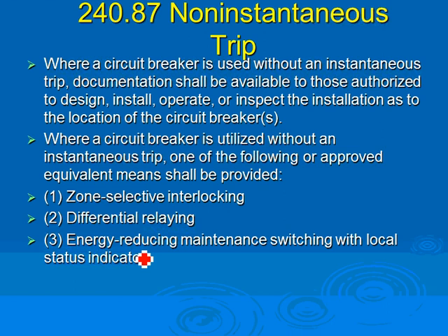When you are to work on this equipment, if you rack that circuit breaker out or rack it in, you work on it energized. What you can do is, on the face of the circuit breaker, you can turn down the instantaneous, which compromises the integrity of your overcurrent protection coordination. Now, if you have a short circuit, they're not going to coordinate. Who cares? We're working on it. It's just a transient. So now I put my energy reduction on, put my suit on, and I can work on it energized. After I'm done, you turn it up again and leave. That's your energy reduction maintenance switch.